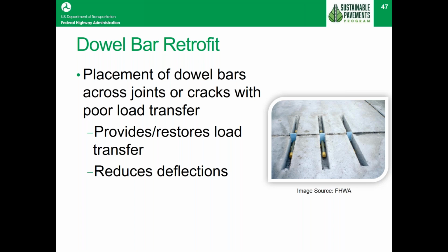More recently, we've been installing dowel bars in pretty much every concrete pavement that's out there, so it's a little bit less of a need today. But nevertheless, you do still see this kind of work going on as well. It's an effective way to add some substantial life to the pavement. It allows that cross-joint support that you definitely need to carry the truck traffic on a major roadway.